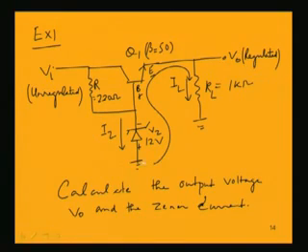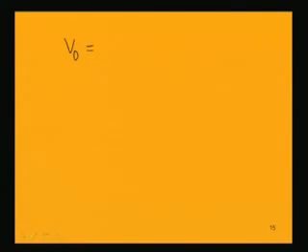This is wrong, this is not plus. Plus will be here and minus will be here, because this is a Zener diode and the polarities should be connected this way: P is negative and N is positive. So we get the rising voltage Vz minus the falling voltage Vbe, that is equal to V naught.